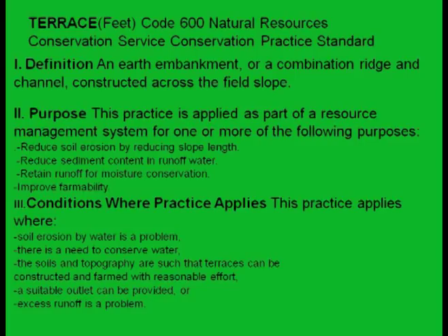Why am I doing this? Do I need to do this? Am I on flat, coarse sand or gravel? I may not need it. The water just goes right in. Is there any evidence ever that the ground goes squish, squish, squish, squish? Well, then you might want to do that. If you have ground that freezes at all and stays frozen through the winter, I would go ahead and put it in, because when you have rain on frozen ground, it's going to go away. So let's have some kind of structure to hold it in place. Let's put in a swale.